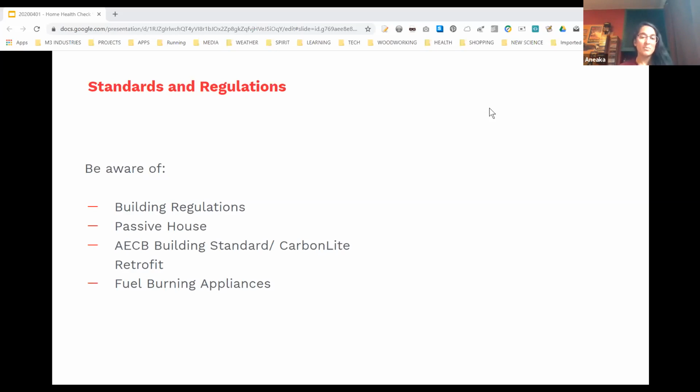Feel free to comment if you do use it every day, but if you don't, I highly recommend getting something called a chimney sheet or a chimney balloon. It'll probably be the best £20 you spend, and I sound like a salesperson, but it's true, because the amount of heat you lose up an open chimney is huge. Diane Hubbard did her dissertation on this when she did a master's at CAT, and she found that the amount of heat loss through an open chimney was equivalent to spending tens of thousands of pounds on insulating your walls, your floors and your roof.